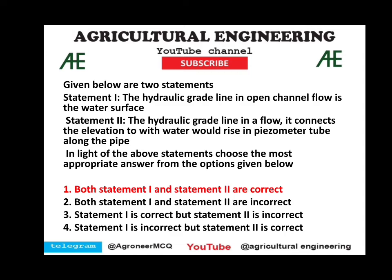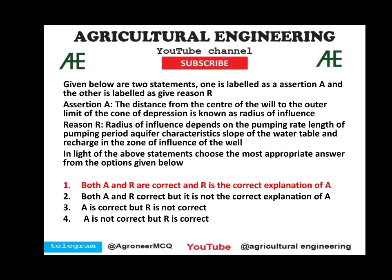Now the hydraulic grade line in open channel flow is the water surface. This one is correct. And statement 2 is the hydraulic grade line in a pipe flow connects the elevation to which water would rise in a piezometric tube along the pipe. This one is also correct. So here two statements, assertion A and reason R. The distance from the center of the well to the outer limit of the cone of depression is known as radius of influence.